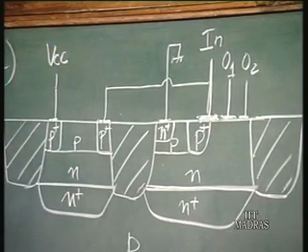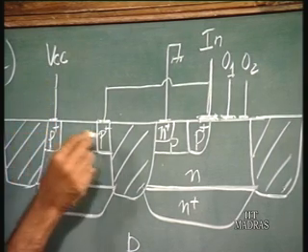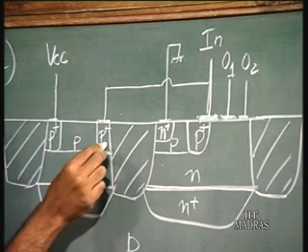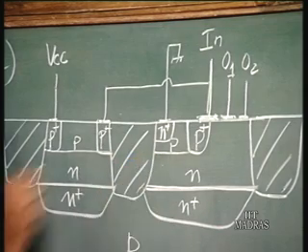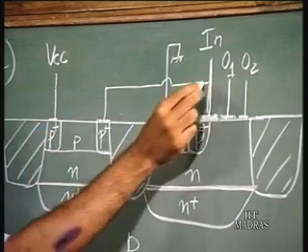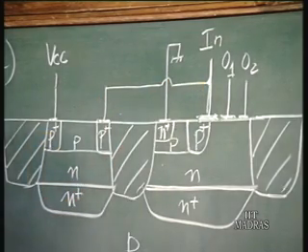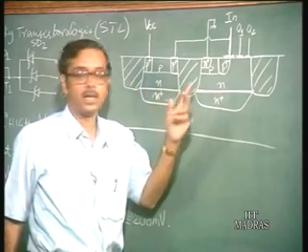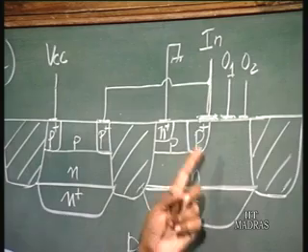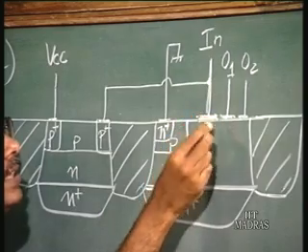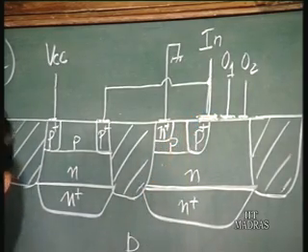Now, if you go back to the circuit, VCC, this is the resistance. This P region forms the resistance, which is the same as the base diffusion of the NPN transistor, that is done simultaneously. So, this is the resistance which goes to the input point, which forms the base of the transistor. Now, you know that in a Schottky transistor, how do you make it a Schottky? This is the collector region. The base contact has an overhang onto the collector region.